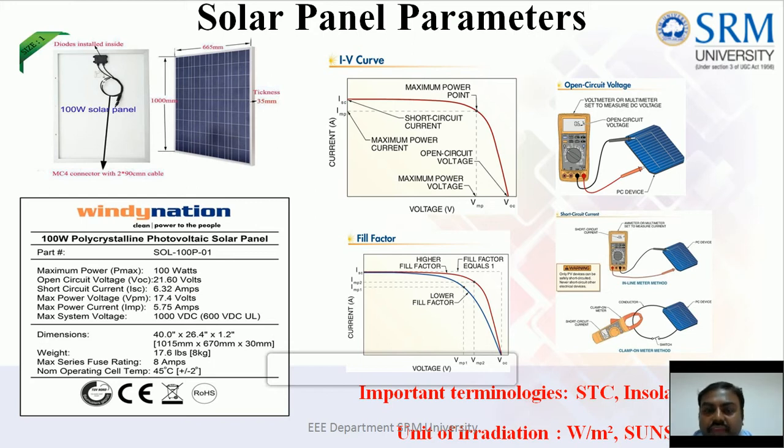So you can see an IV curve which essentially has the parameters we are seeing in the data sheet, of course. The voltage is on the x-axis and current on the y-axis. You can see the short circuit current. Short circuit current forms the upper limit in the y-axis. When I say short circuit current ISC, that refers to the impedance being very low, so low that this current is maximum, called ISC. R is equal to 0.